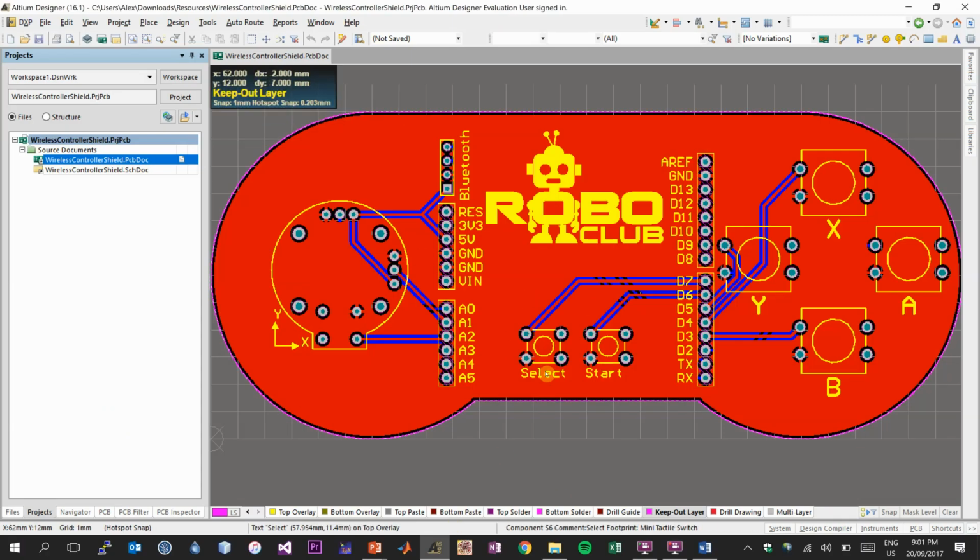Typically, you want to place mounting holes wherever there may be design instability. Fortunately, this project has a shield at the very center, so there's going to be mechanical stability via placing the shield connections. However, it may also be beneficial to have additional mounting holes throughout your design. So if you have a square design, it's typical to place mounting holes in each corner of that board outline. So for me, I'm just going to place a mounting hole here, and at the top and bottom on the right-hand handles.